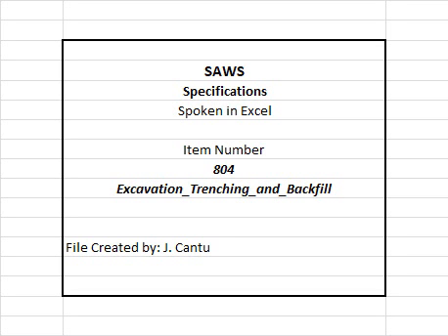of the pipe. F. Secondary backfill is defined as backfill from 1 foot above the top of the pipe to the top of the trench or bottom of pavement section. G. Secondary backfill shall generally consist of materials removed from the trench and shall be free of brush, debris, and trash.